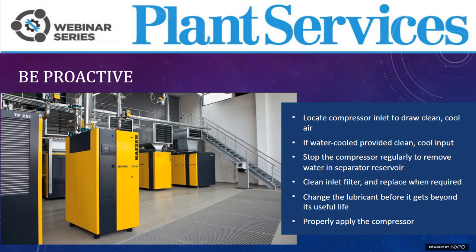Be proactive. Don't shy away from any of these types of analysis, but keep in mind that operating conditions in your compressor room are going to have a direct effect on the reliability of your compressor. Just because you're streaming data doesn't mean you don't need to go out and check the compressor room. The data is going to help you figure out your trends, but when you walk into a compressor room, you can tell if there are going to be issues or not based on the environment and the condition of the equipment. The items listed above are going to ensure that you've got a reliable and efficient system to start with.